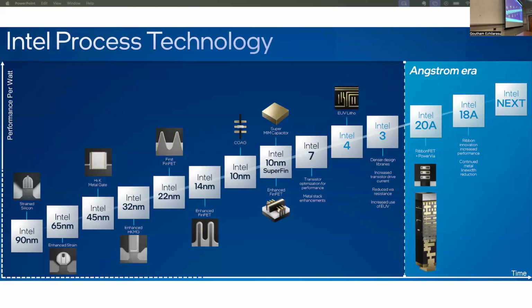So in this region, silicon is exposed, in this region, silicon is exposed, and here in the drain also the silicon is exposed. Then you deposit titanium or nickel, and when you heat, the titanium or nickel alloys with the silicon, and you get silicide here, here, and here, right? So this is another place where the sidewall spacer is useful because it prevents the silicide from forming on the side. Otherwise, this will short out the source and drain, right? Sorry, the source and the gate, right?